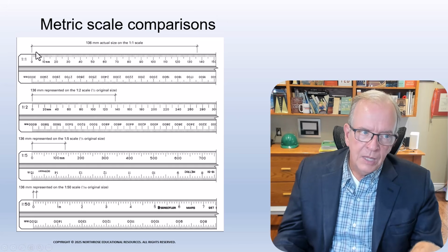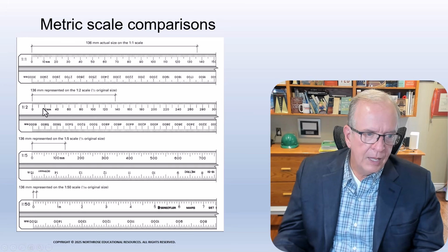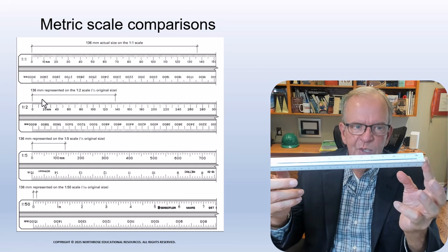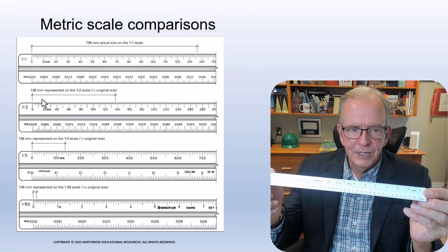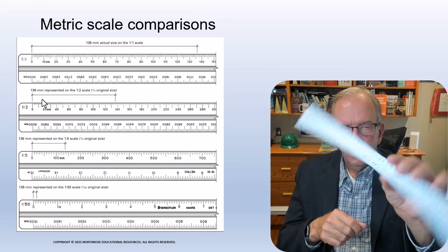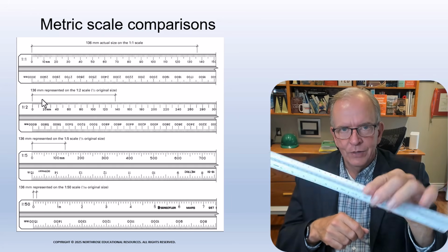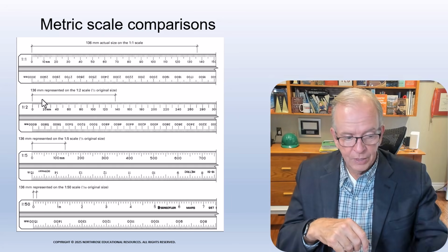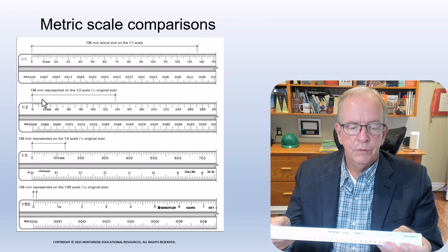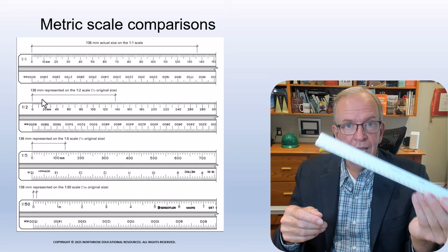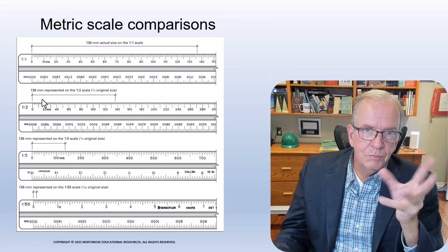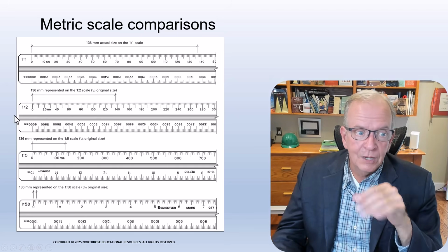With scales, it changes by the scale. And there are these scale rulers. What the scale rulers do is they've got these scales printed on them. One ruler may have 6 different scales on it in metric. In Imperial, I forget, it's something like 11 or 12 scales on one ruler. So that's a lot, right? And that means you've got to adjust every time you look at the scale for what it is.